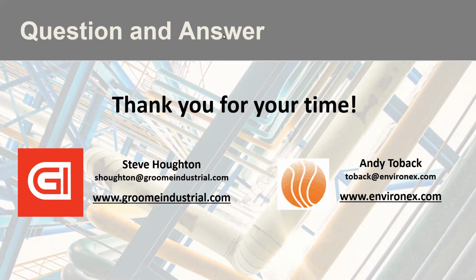Let's see. We got a particular plant that ammonia slip is the concern primarily, not necessarily ROI. They're concerned with the impact of ammonia slip on the tubes and performance losses due to ABS, or ammonium bisulfate fouling. Are there better ways to correlate the AIG tuning with less tube fouling and performance losses? If we had more than 45 minutes.